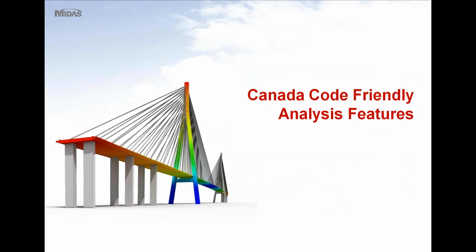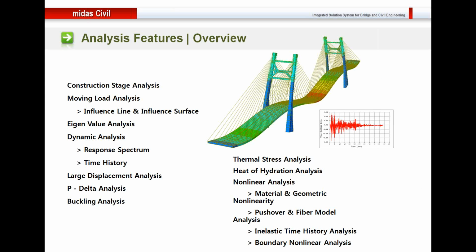Now let us talk about the Canada code-friendly analysis features that Midas Civil provides you with. First of all, let me give you a basic overview of different analysis features that Midas Civil has. Apart from general static analysis, linear static analysis, you can perform construction stage analysis considering the time-dependent behavior of concrete. You can perform moving load analysis. If you want to perform influence line or influence surface analysis, you can do that in Midas Civil. You can perform eigenvalue analysis. Dynamic analysis is supported. You can perform large displacement analysis, P-delta analysis, or buckling analysis.